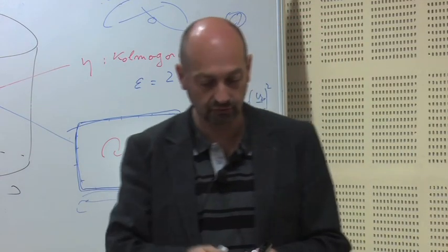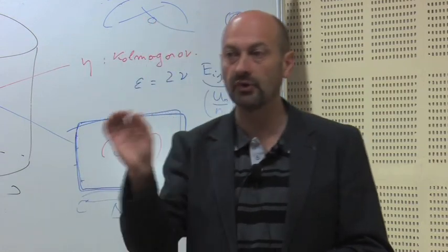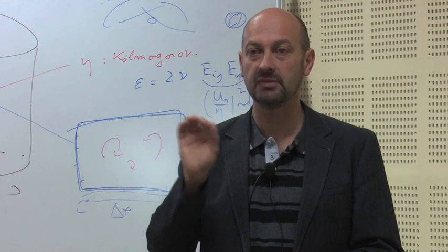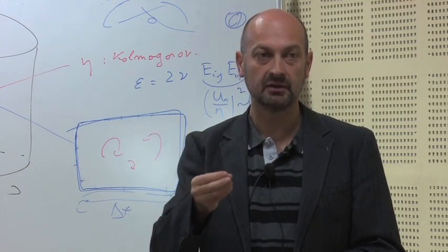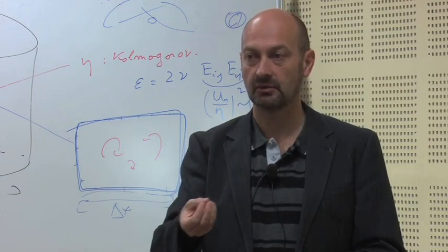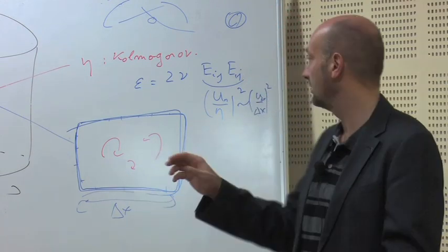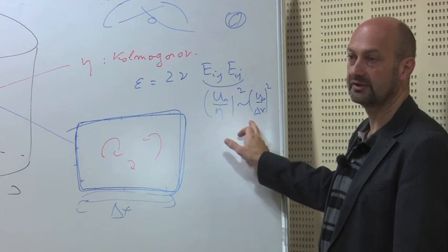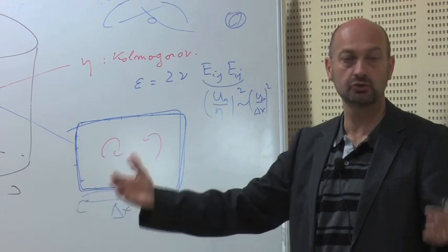At some point you may use a computer software, and you will select some models of turbulent viscosity. Turbulent viscosity means I'm going to plug in a model which generates artificial viscosity, numerical viscosity, modeling viscosity, which compensates for the lack of dissipation because I'm solving the flow with a length scale which is too big.